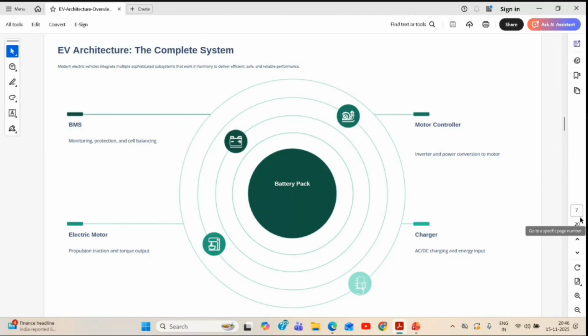It is advisable that, okay, you are dealing with the embedded part, or you have some expertise. Still, you should have a little bit of knowledge regarding chemistries, anode, and cathode. If you are using one type of lithium battery, which one is your anode, which one is your cathode, how is it behaving? How is lithium titanate different from manganese, how is LFP different from titanate? Why LFP right now? Many manufacturers are using LFP.